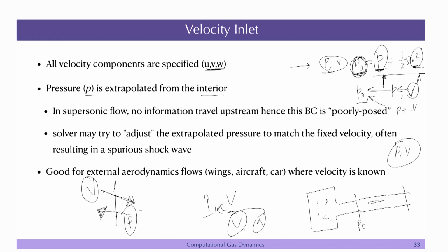So, in the case of supersonic flow, you can try doing this, because in supersonic flow, as we will shortly see, either all the characteristics are incoming or all outgoing, right. So, in that case you can basically specify both P and V and you can work it out. Okay.